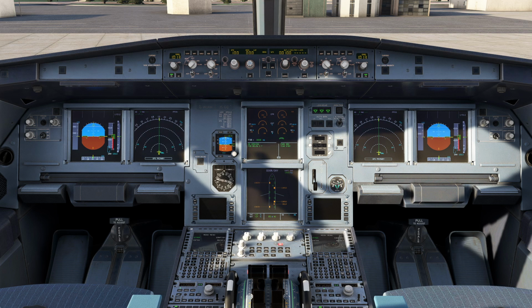Others go to the flight warning computers, which use them to generate ECAM messages and aural alerts through the loudspeakers. We also have two flight warning computers. Flight warning computers generate alerts, messages, memos, aural alerts, and also synthetic voice messages.